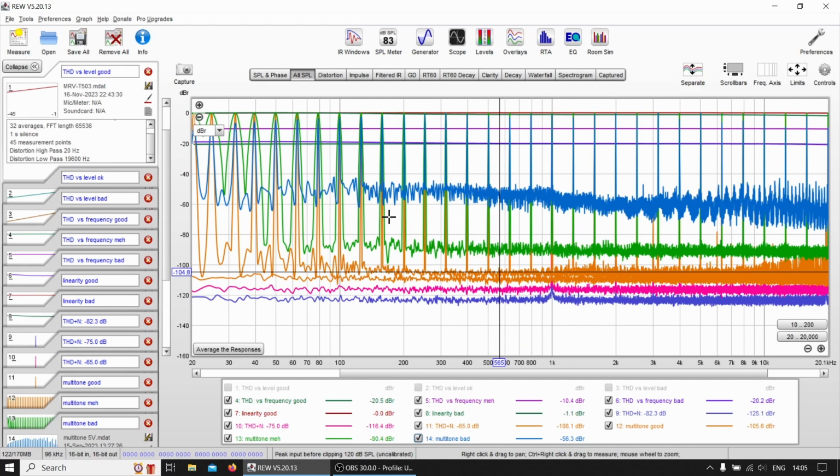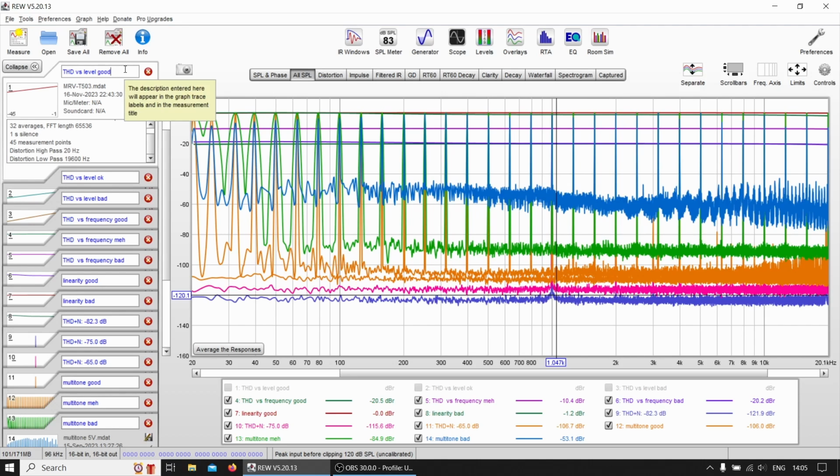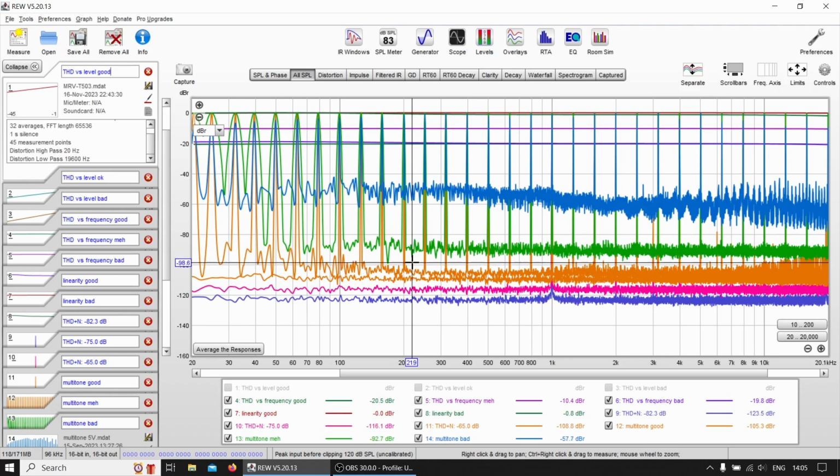So yeah, these are the measurements that I usually do when measuring amplifiers. I do them in a resistive load of 4 ohms, then at 2 ohms, and then I do bridged channels and so on, because the performance of an amplifier is going to vary depending on the load or whether you bridge channels or not. And again, it's very interesting to see how it depends on those things. So there usually are a lot of measurements, but just for you to see.